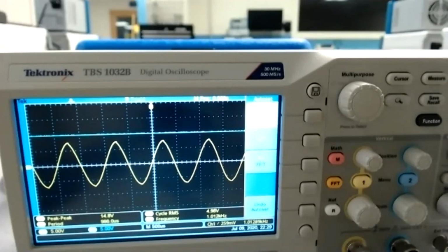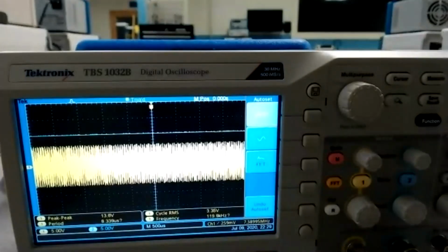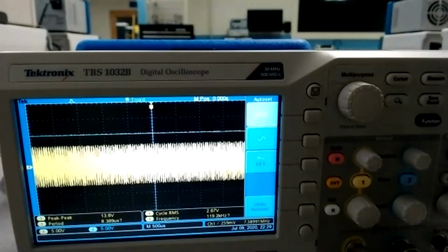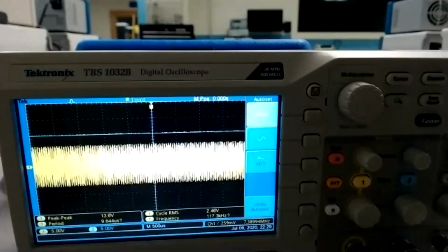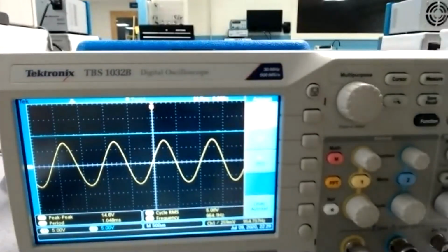And this is very important to remember. You have to take the voltage RMS, in this case 5 volts, and divide it by the magic number. What is the magic number? 0.707. So take that 5 and divide it by 0.707. If you take out your calculator real quick, 5 divided by 0.707, you get 7.07